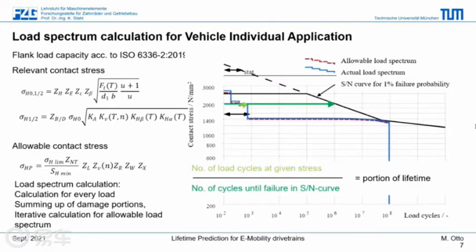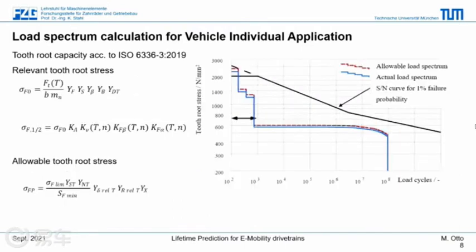And this is how this red curve, which is in this graphic nearly identical to the blue curve, is determined. The load spectrum is scaled, the full calculation is run again, and then iteratively the load spectrum is scaled to a life usage of 100%. And then we have some information on how critical our load spectrum is. So, quite a complex procedure.